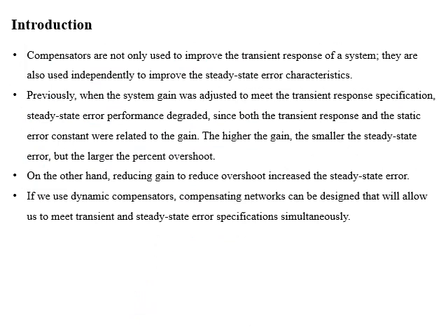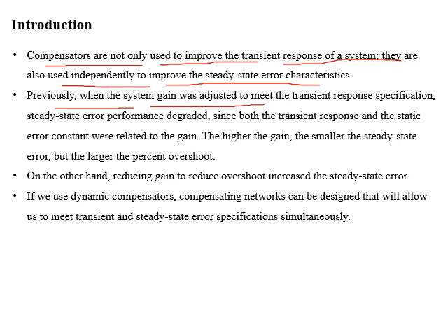Dear students, compensators are not only used to improve the transient response, but with them we can also improve steady-state error characteristics independently. Previously, when the gain of the system was adjusted to meet the transient response specification, the steady-state error performance was degraded because both transient response and static error constants are related to the gain.